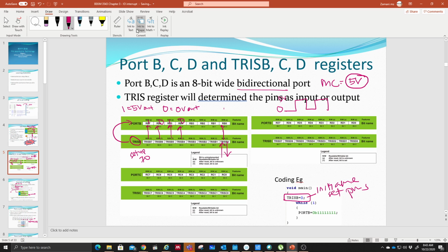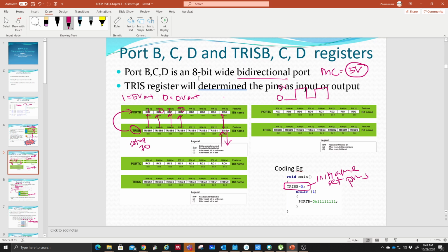Okay, so there are port B, C, and D, which are nearly the same. So that's why most of the I/O I'm going to put over here, whereas port A and port E I normally reserve for any analog input. It's much better. I'm not going to use the analog input, because you have the extra resources over here, so just use these for the I/O. Next one.